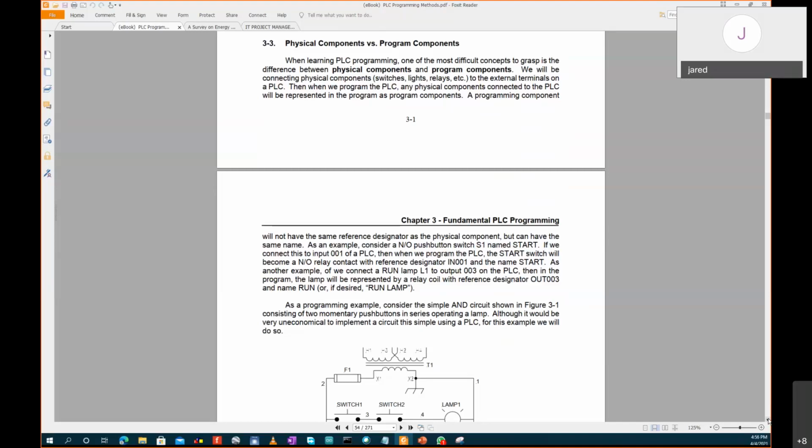If it's a pressure sensor, just write pressure sensor, and even give more details: which range, 0 to 16 bar, or 0 to 5 bar, that kind of thing. So it becomes easier for you to relate them in the field. If you give them arbitrary names, like switch 1, switch 2, switch 3, you'll have a big problem, because you have maybe 20 switches in a control panel and you don't know which is which.